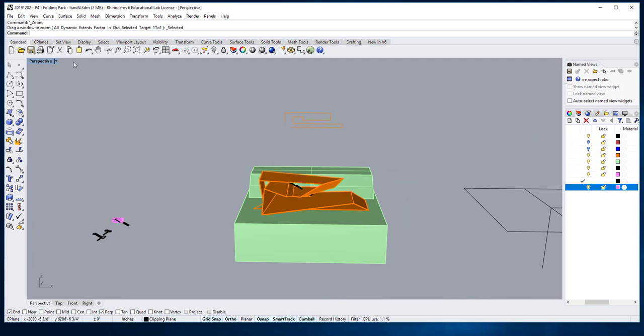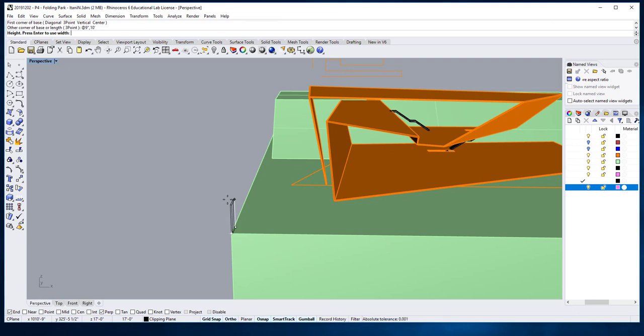So I'm going to make a solid box to make the walls. Pick a point and type at 9 inches, comma, 10 feet. Enter. Then give it a height. At height, say 15 feet 3 inches.